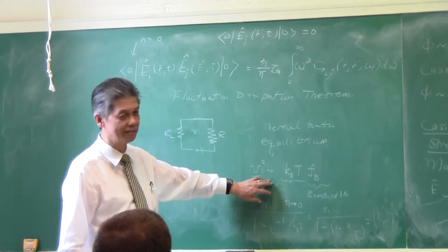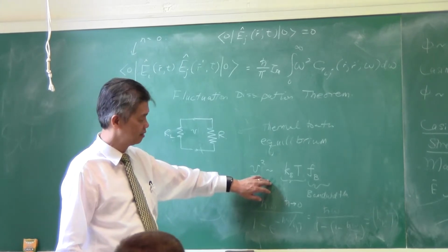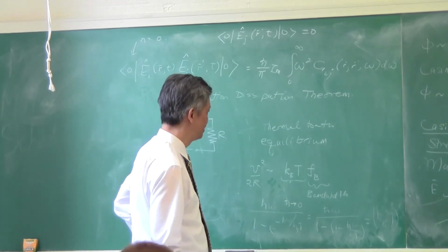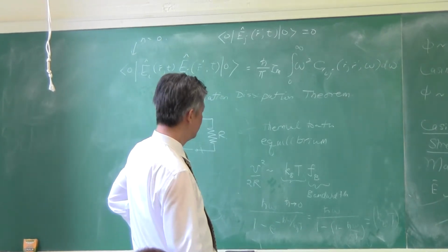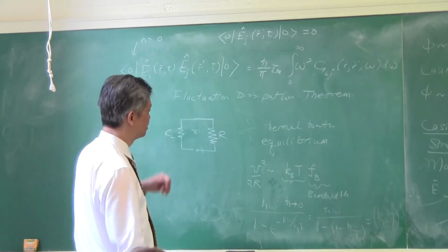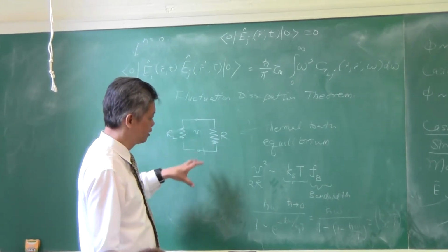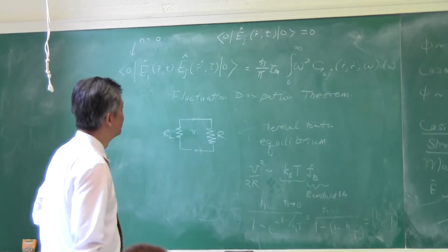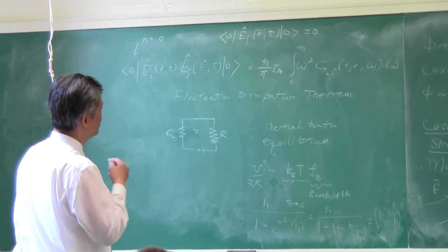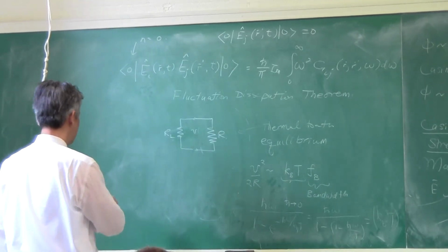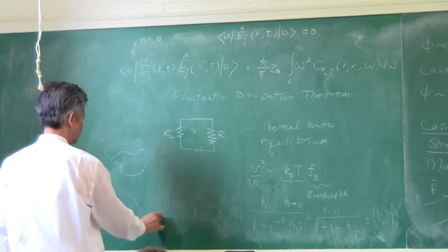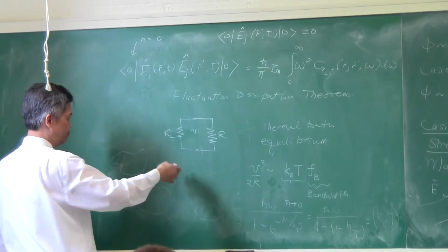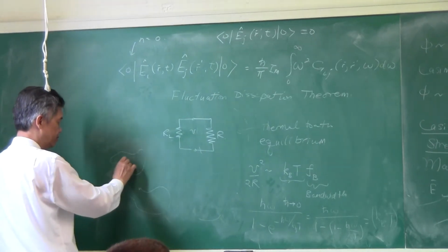It's been used by electrical engineering a lot. If you calculate thermal noise in your circuit, you invoke this law, which is actually a subset of Planck's law. And the fluctuation dissipation theorem says that the kind of energy that you can acquire from the environment is proportional to this thing, because you're in thermal equilibrium. And similarly, the fluctuation dissipation theorem says that if you have a very complicated object, this object is going to be in thermal equilibrium with the rest of the world,